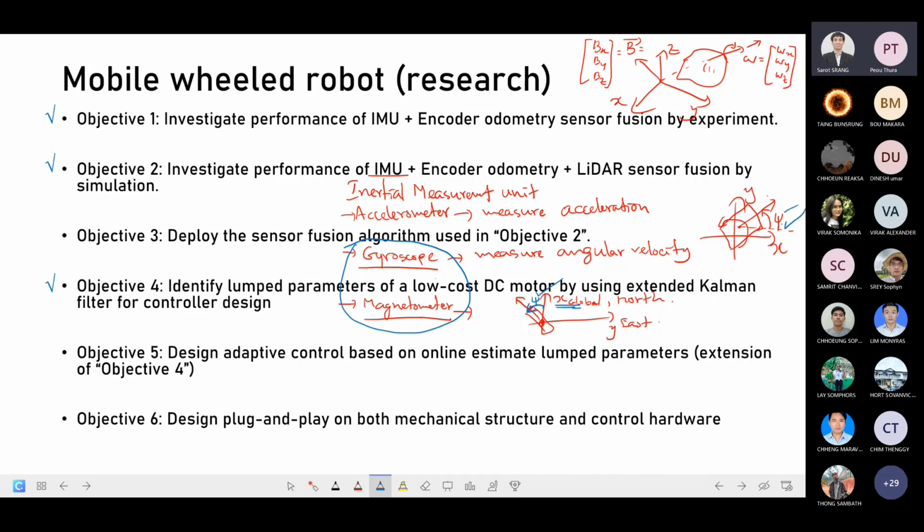I explained before that with a gyroscope we can only measure angular velocity, and we can use kinematics to compute angle, but it is in a relative term. But the magnetometer measures the angle in absolute terms because it gives information with respect to the north axis. That's why we need both of them. The accelerometer can measure acceleration, and we can compute velocity and position from it, but it can also be fused with other sensors like the gyroscope and magnetometer to give a good orientation in space.